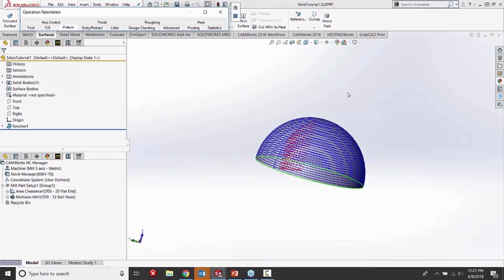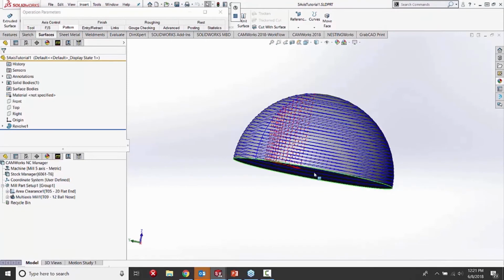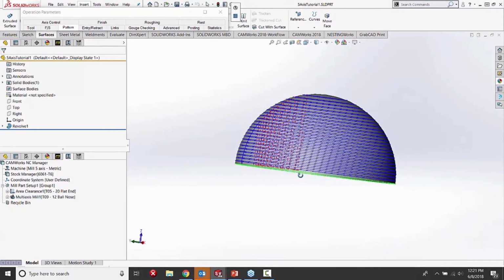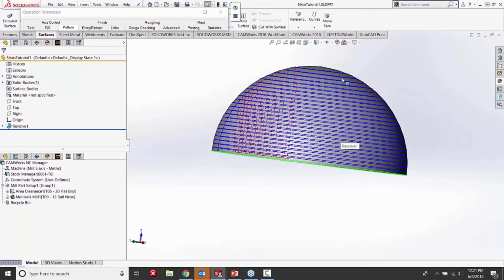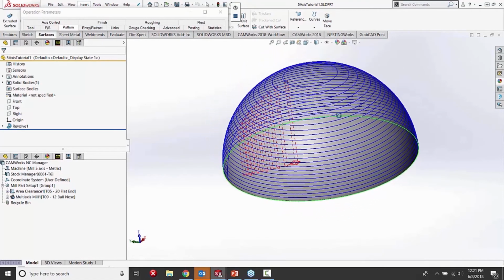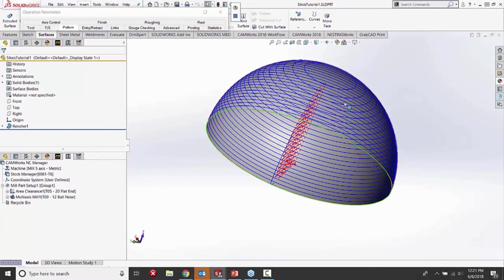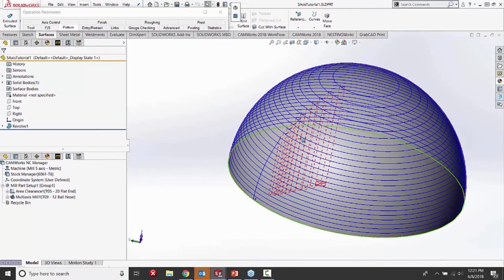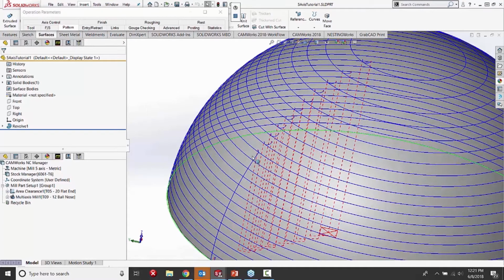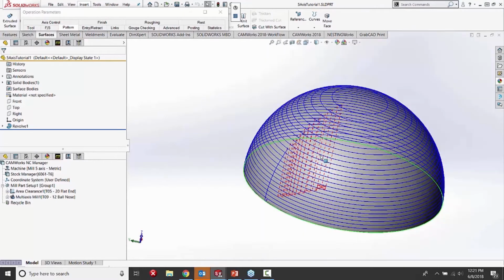Right, so we've essentially taken that bottom surface and created an offset surface from it, at a specified amount going upward, and now the toolpath runs along that. So it's looking a little bit better, like a toolpath that makes a little bit more sense for this part. What I'm still not happy about is the way the tool is lifting off the part, and obviously we still have some issues with our entries and retracts.